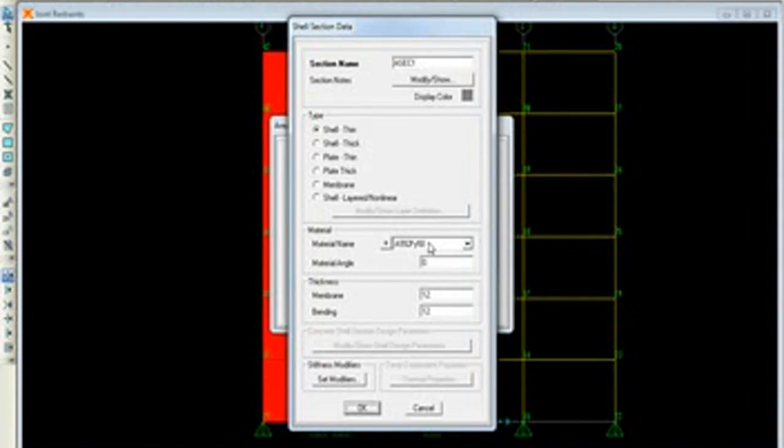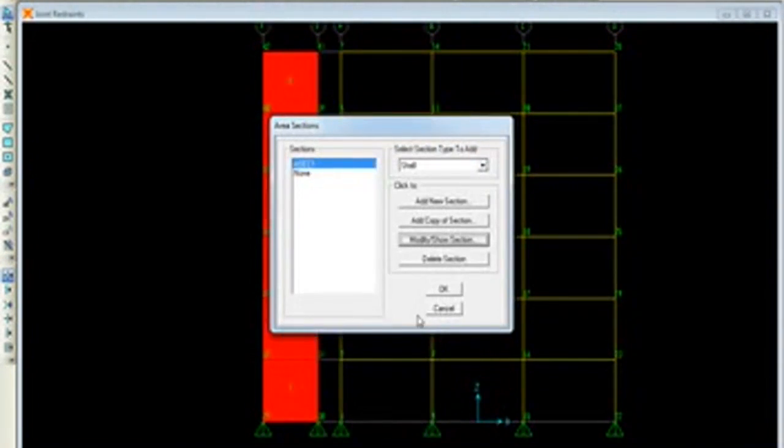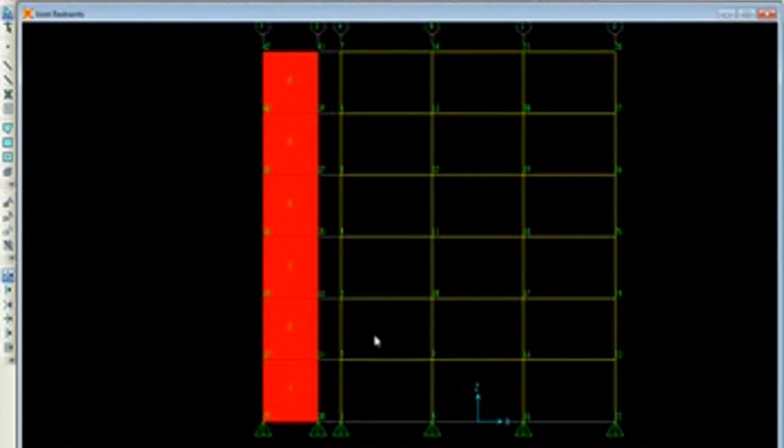So I'll try to specify the thicknesses of the wall sections over here. Let the member be 6 inches of thickness. That means almost 15 centimeters of thickness. So let ASEC be the same, because while I am selecting, I have given ASEC for these members. So please be careful with the selection process. So now I have specified members.